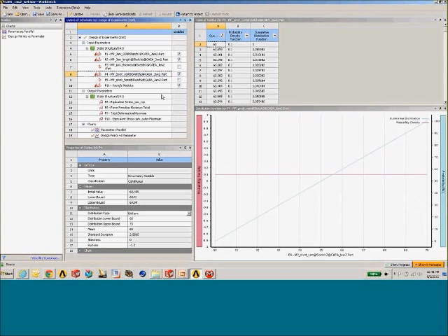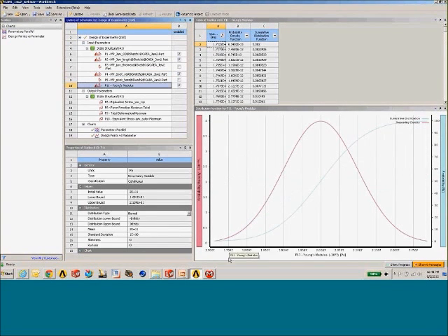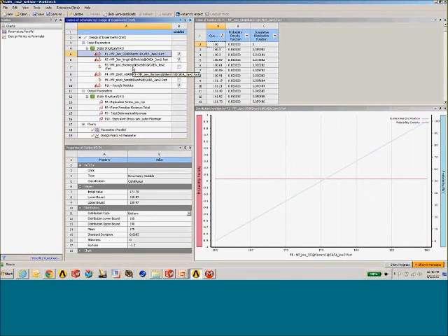So, for instance, if I happen to have some information on my Young's modulus that represents something like a normal distribution or a bell curve, I can assign the input or the probability based on the mean and the standard deviation to give me a distribution of that sort for my Young's modulus. In the case of something like a dimensional value, you may only know the min and the max value for that dimension. So you may use something like a uniform distribution. Or if you had some additional information like a common point, you could use a triangular distribution.